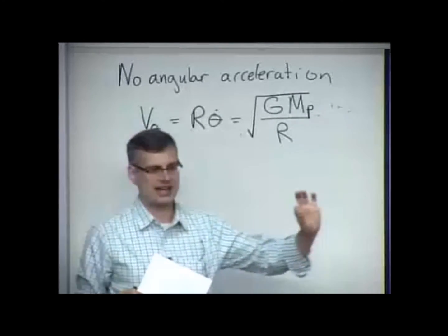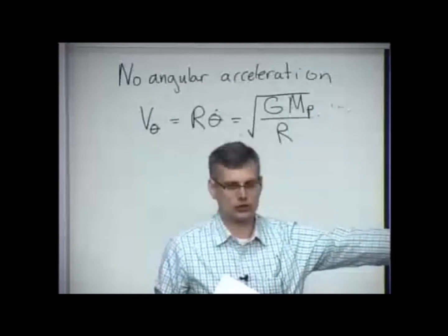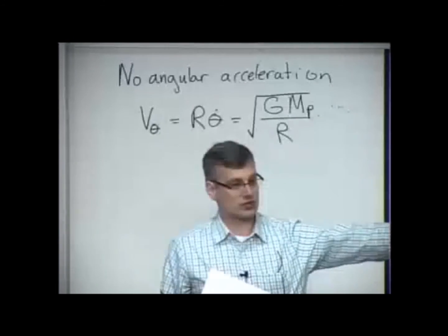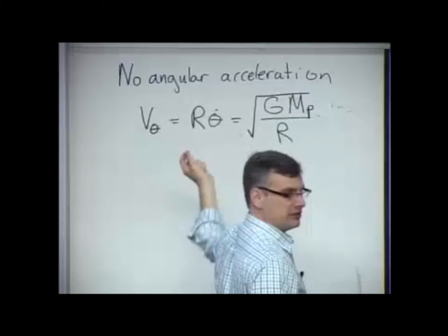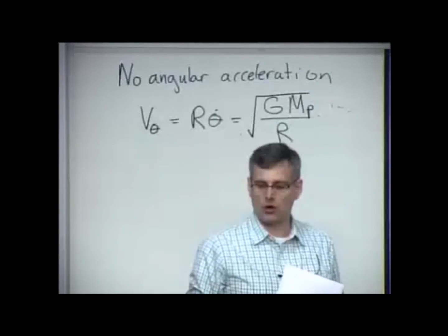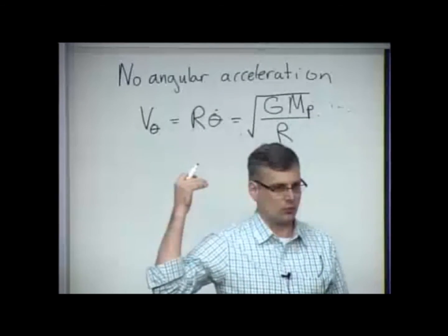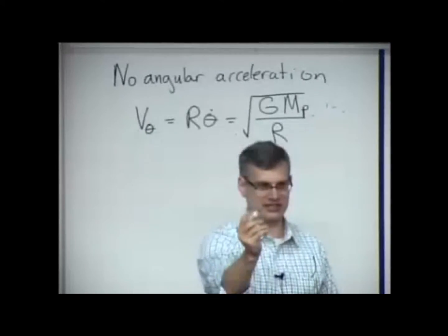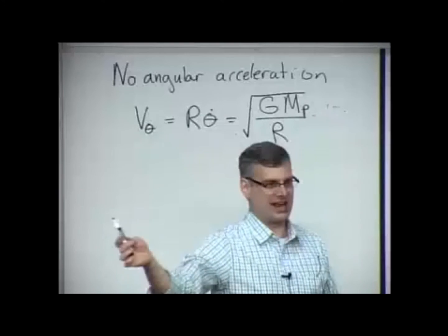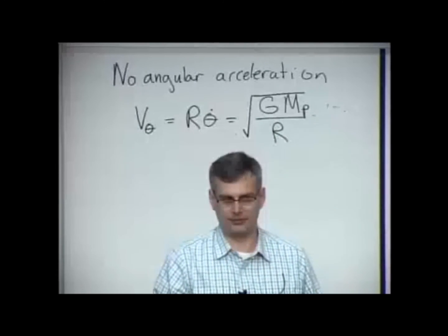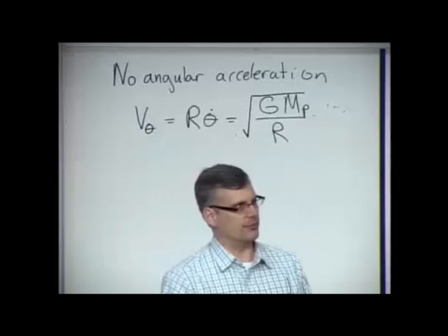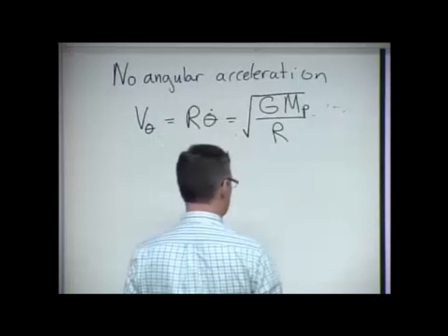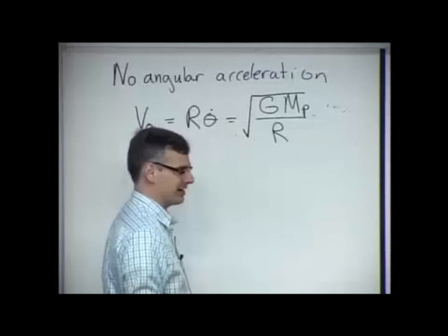The farther you move the satellite away from the planet, the slower it travels to remain in a stable circular orbit. So it travels slower, and it has a longer circumference to travel, which means as you go out further and further, you really slow down what we would call the orbital period, the time it takes the spacecraft or satellite to make an entire sweep in orbit. We'll mention this when we get to my favorite calculation in the class, which is coming up in a few minutes.